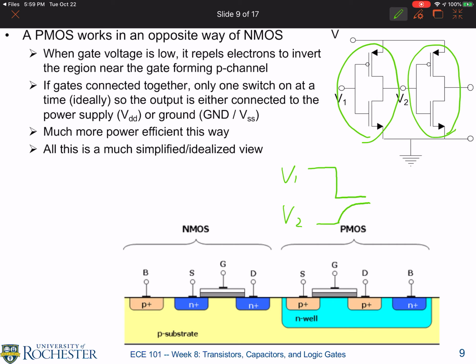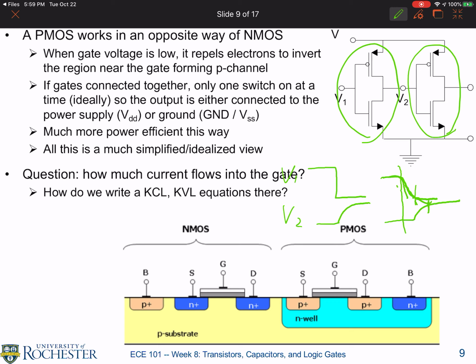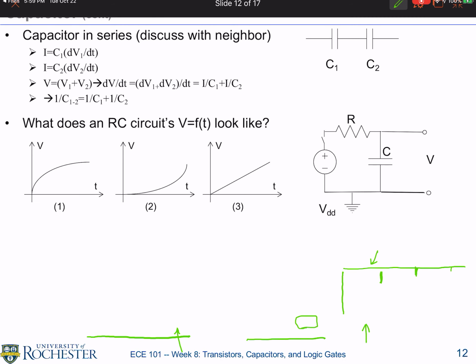And in fact, even this is simplified analysis. In reality, there is some delay that triggers the next stage before it starts to gradually change. So from one stage to another stage, we start to change here, we get to steady state here in the input, but we only get to steady state a little bit later in the next stage. That's why there's finite speed propagation. It's not infinitely fast. Okay, so that's really the most important message for this.